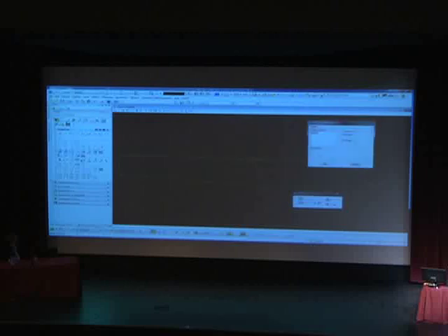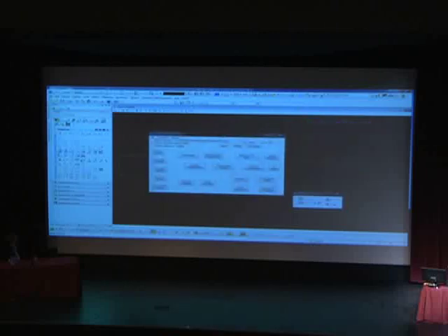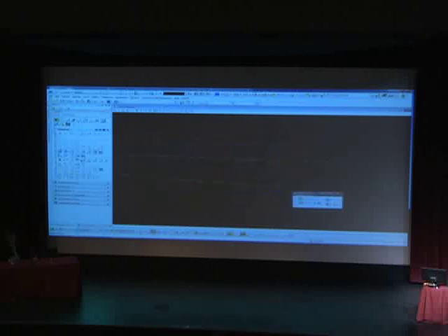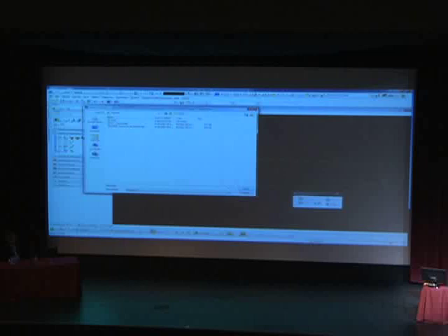All right, now I went to classic tools, and I'm connecting to my PRJ. This is a dialog box everyone's familiar with. All our tools are still there. You can do the report cross-section quantities, you can do the vertical alignment generator, everything is still there, so you all can still use that. Now the main difference between the new software and the old software is the cross-sections. So your shape files are not going to be there, your criteria files, thank God, are not going to be there. At least that's my opinion.